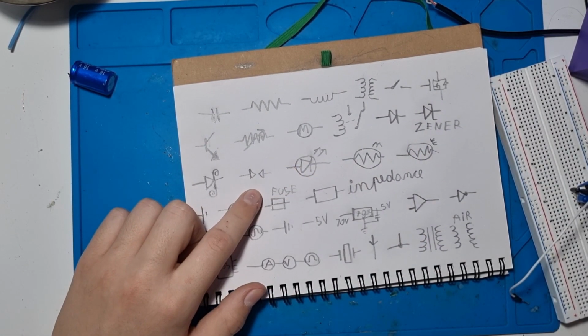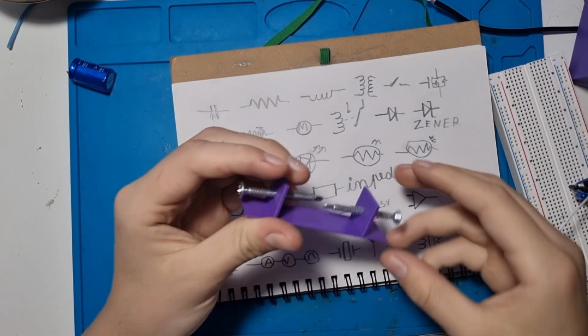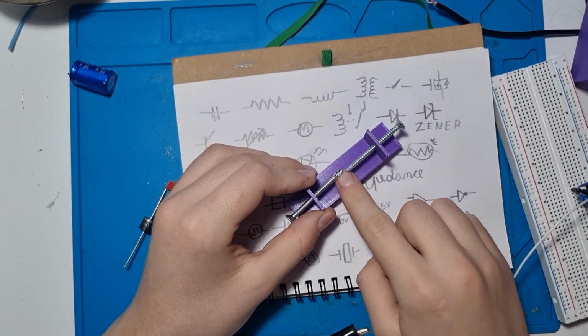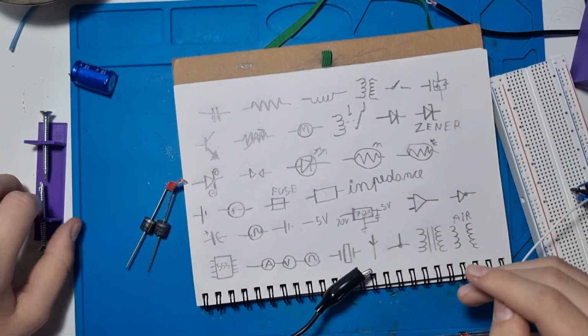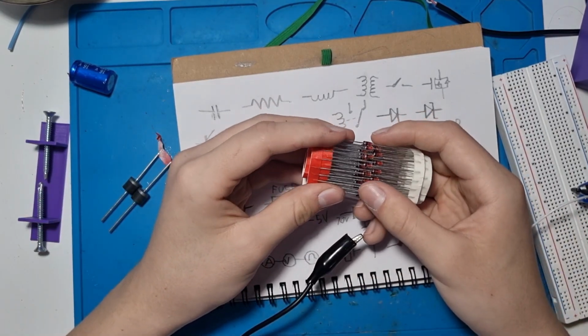This is a spark gap. So you can use a spark gap as a switch for high voltages. When a voltage goes over the spark gap voltage limit, let's say a few kilovolts, an arc goes across this and turns the circuit on. This is a regular Schottky diode, it's very big, and these are some Zener diodes, usually glass body.